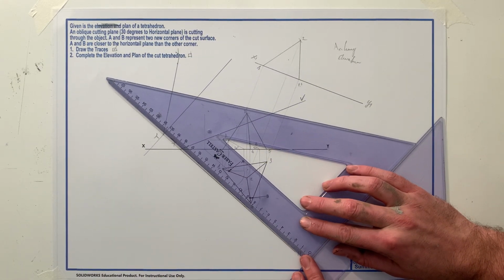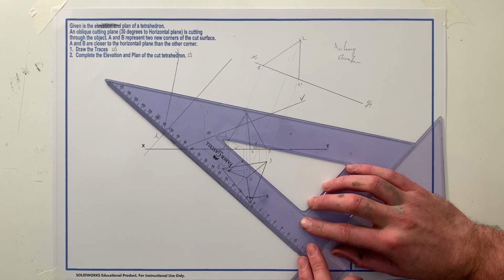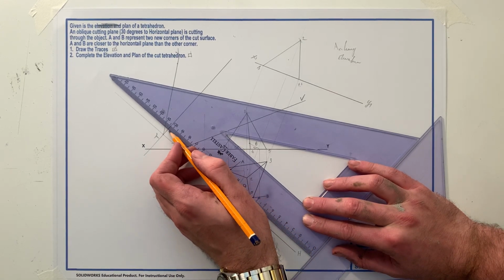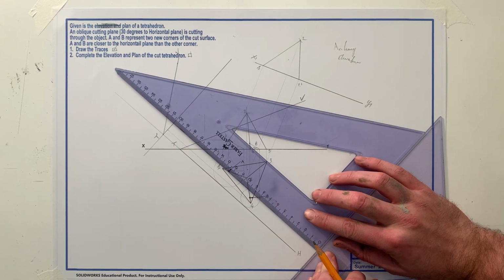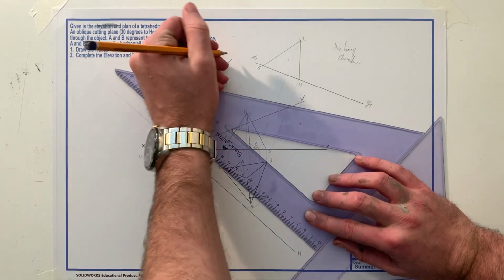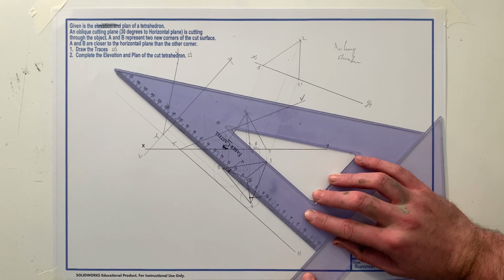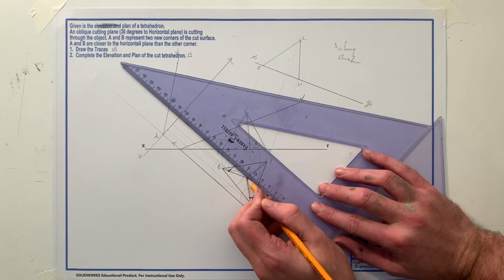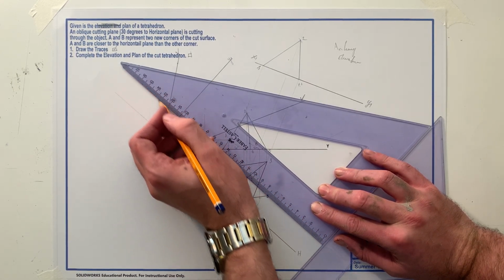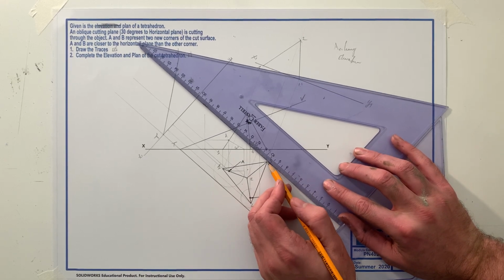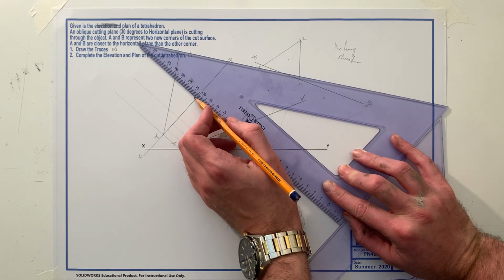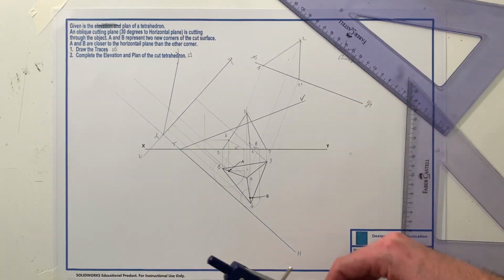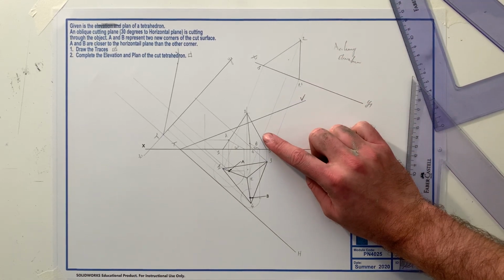Take all the rest of the points that I need up. Remember, this is the first auxiliary as well, x1, y1. All the points are going to be resting on the x1, y1 except for point 2, which is the apex. Take my height either from my auxiliary elevation above here or my elevation here.